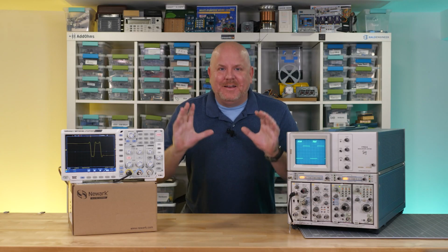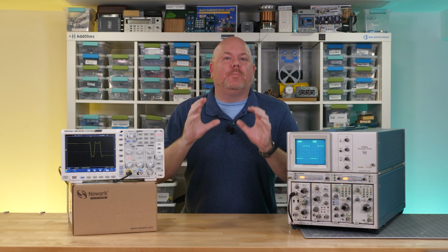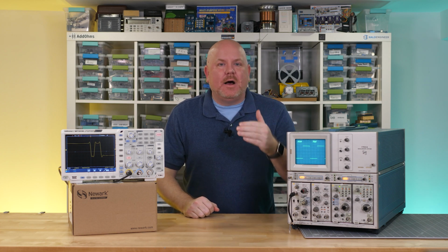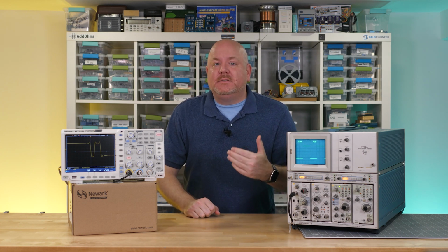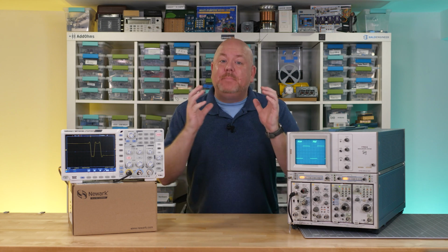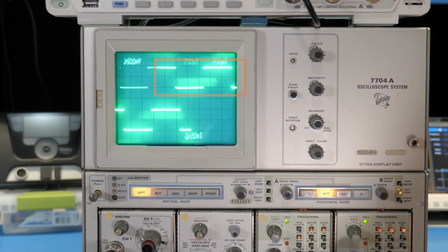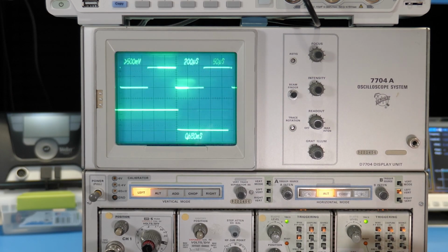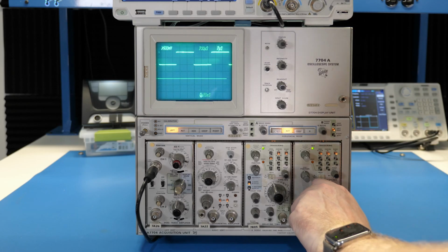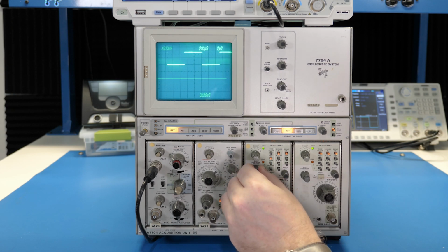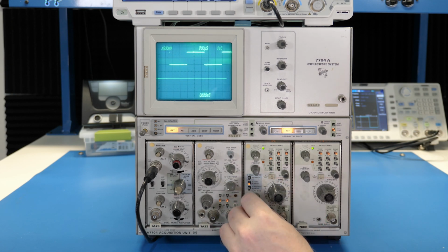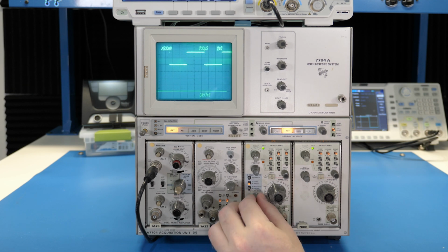Okay, but we haven't gotten to the really cool part yet. The delaying module is called delaying because it can delay how long until the B module triggers. When I enable the delay mode, we see a bright spot on the A or top trace. As I make adjustments to the B trace's time base and delay time, that spot moves around. It is showing us how long the B module waits to trigger and how much time the bottom trace is displaying. In other words, it's like the digital scope and the zoom window.